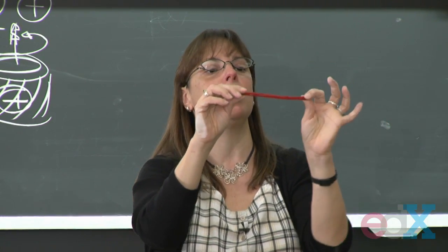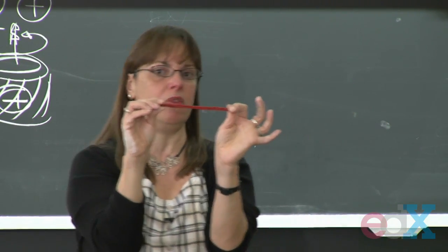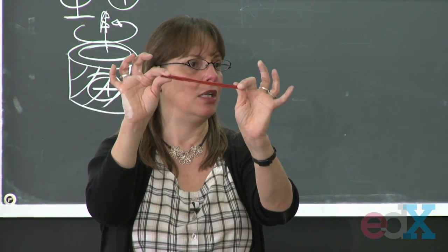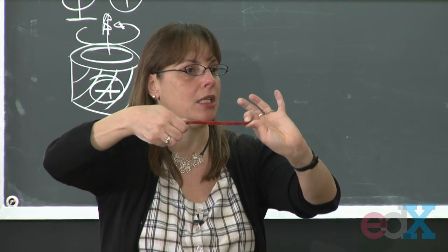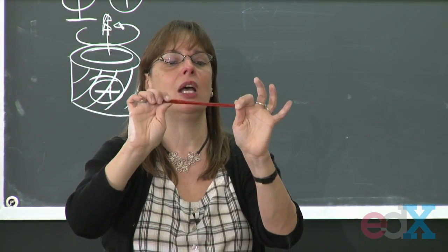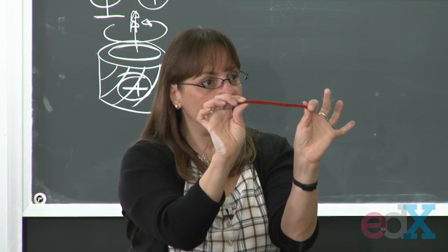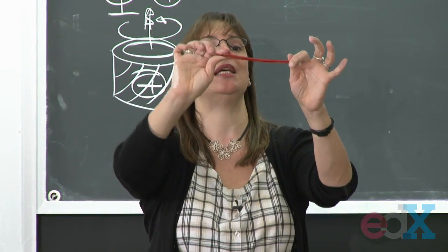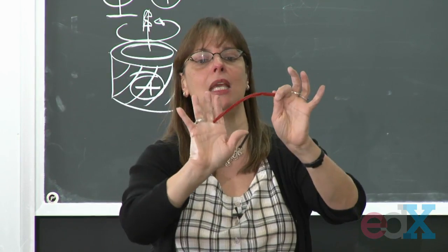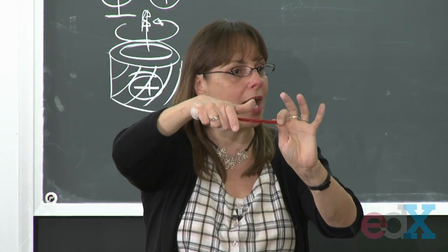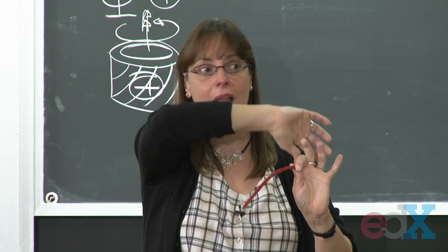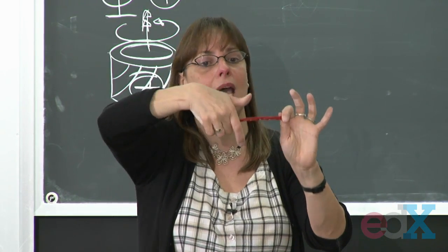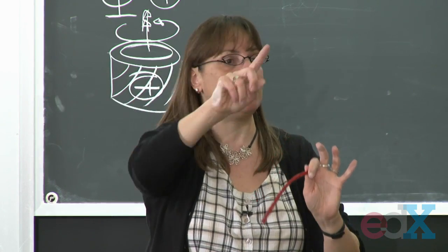Okay. So if I imagine that this Twizzler, before it was manufactured and set in this shape, used to be straight. Then somebody went in and twisted it. And I ask myself, the angle of twist that they gave to this Twizzler, is it a positive angle of twist or negative? Then I see the way it's twisted, and I see if my thumbs go in or out, my right hand thumb, not my left hand, because that's opposite. My right hand, does it go in or out? It twists that way. It goes in, is a negative phi.